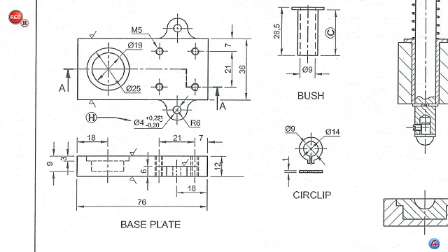So number 16, request for the minimum tolerance. So what we need to do is to take 4 minus 0.20, and that is going to give you 3.80. So number 16 will be 3.80. Number 17, we will have to take the 4 and we will have to add it to 0.25, and your answer will be 4.25 for number 17. Please ensure that you write out the entire calculation to attain 2 marks each.